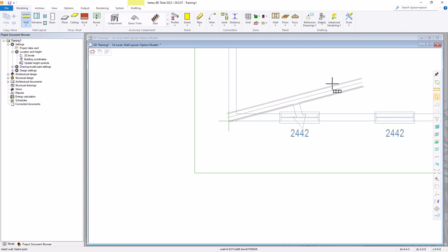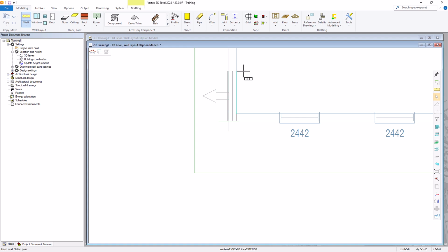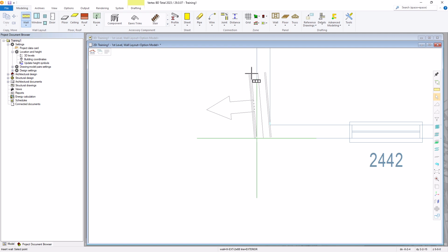Let's go back and hit the U key. I'm going to draw vertical, right click, and fix it back to the opposite side. Now I'm going to select the I key. It's important that we are accurate when we're drawing. We don't want any skews in our lines. So having true straight walls is important so that when we get down later to the framing process, things look correct and we don't run into any issues due to bad input like skewed lines. I'll select the I key to set the Y-axis constraint. To set the X-axis constraint, select the U key.